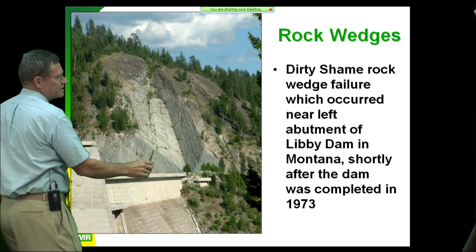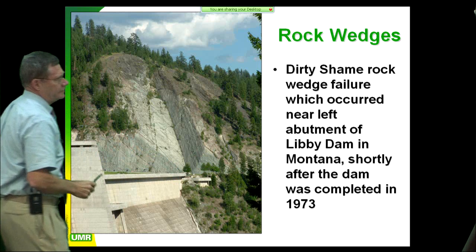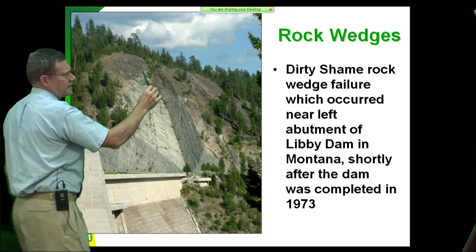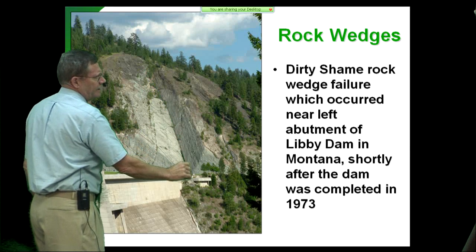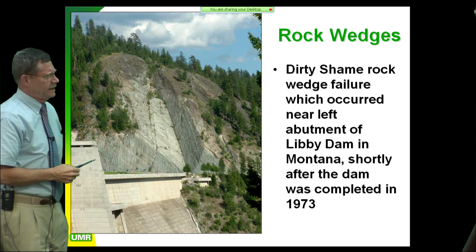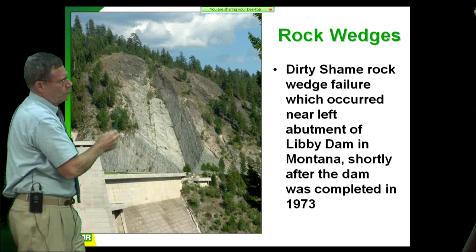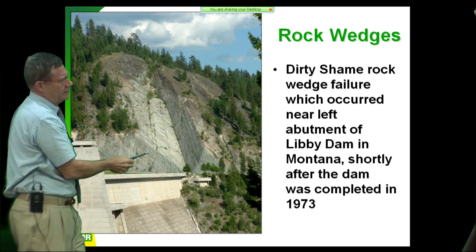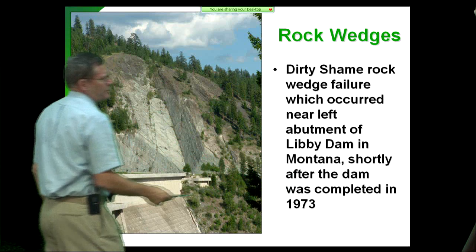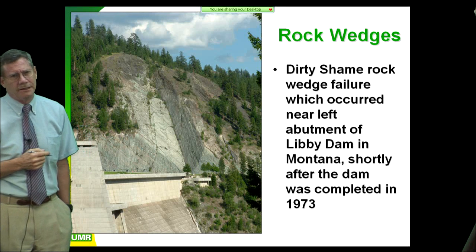And you can see on this cut slope they made right here, the cut slope was about 1/2 to 1. It's very, very steep. And so this thing came out and daylighted in that, and then of course they had a consultants panel, and the panel wisely pointed out to them, well, this geometry is the maximum wedge you could have for that cut. What about your powerhouse down here? You got the same geometry sitting right on top of your powerhouse. What if you have an earthquake? And so that's why the project was delayed 3 years.